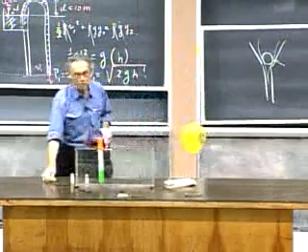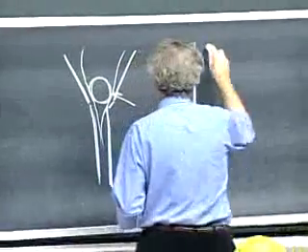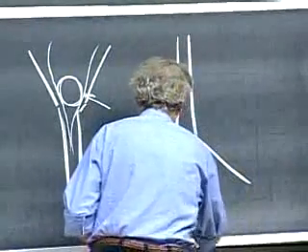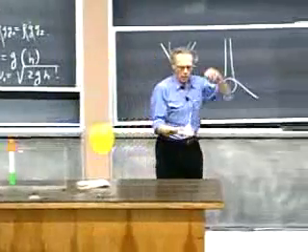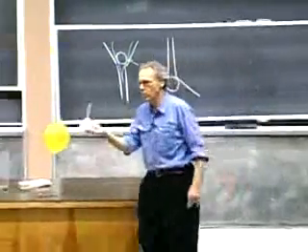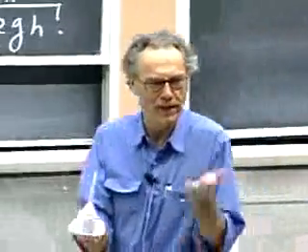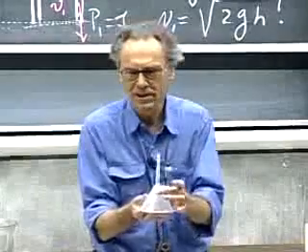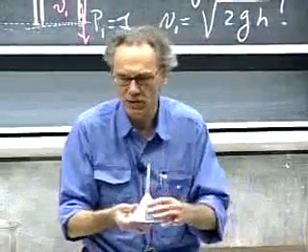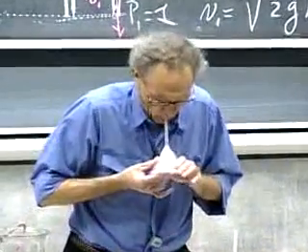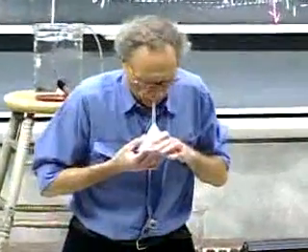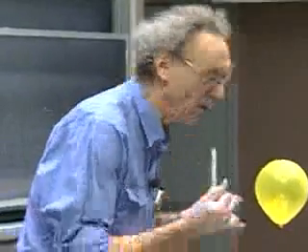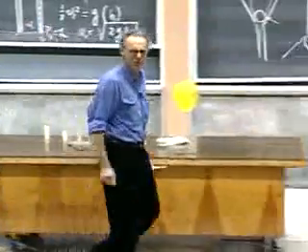And to give you the conclusive proof of that, I will do it this way. I will put the ping pong ball like so. And I'm going to blow like this. And if I blow hard enough, the ping pong ball will stay in there, because I generate a lower pressure right here where the passage is the smallest. But I have to blow quite hard. You see that? Is that amazing? That's the reason why she couldn't get it up. That's what Bernoulli does for you. Not so intuitive, is it?